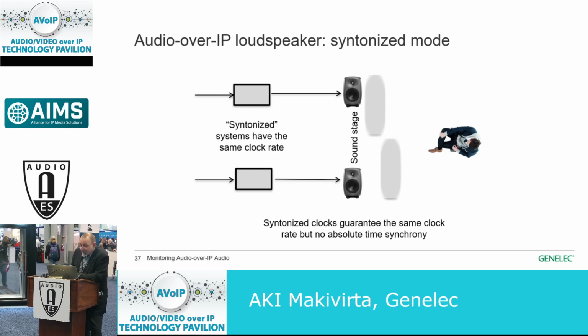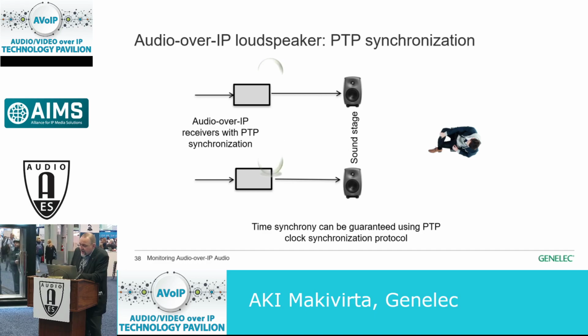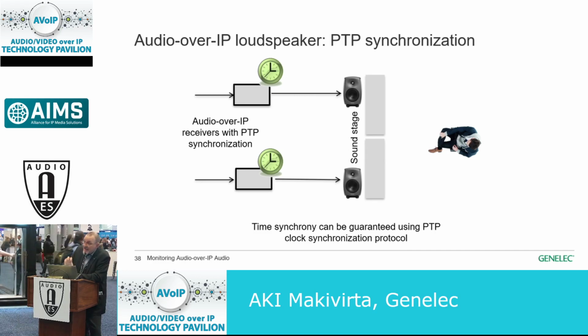So this mode is working similar to your traditional house sync. What we would like to have is the absolute time being correct. And this we can have by bringing in the PTP synchronization. And then this actually ensures that all these different devices have correctly and exactly the same understanding of the absolute time. So that when these devices play out audio, it's happening at exactly the same moment of time. Everything is in phase and in sync, and we can create the sound images correctly.